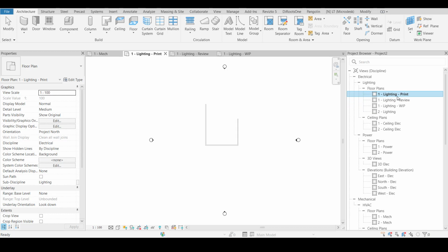Export is normally done in 3D for Navisworks or other software like Revit or Solibri, exporting our views in a particular manner so that they go and club and federate with the other discipline models. That is not applicable for 2D views, only for 3D views. So in our case we are going to use four use cases of the same views. Now, how many views do we need? As many as the floors we have and the services we are going to deliver.